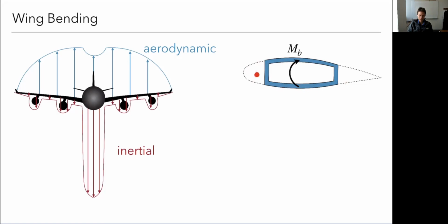Along the trailing edge and leading edge, there's very little structure. It's not carrying loads, it's just for shape. So structurally, we just need this kind of shape, but aerodynamically, of course, we want an airfoil shape. So we need a thin skin to provide that shape, but it's not going to carry any loading. And again, you might see this if you look out the window sometime when you're flying. You might see on top of the wing these painted lines, and then an area that says something like no step, or you don't walk there, because if you drop tools there, you walk there, right?